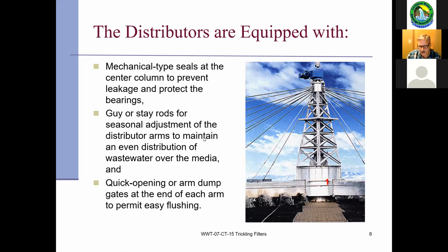Just trying to find a good picture for you. So this is the distribution system I was just talking about. So as this arm moves around, it's distributing the flow around throughout the tank. It's picking up O2 as it's dropping from this distribution arm onto the media. This media, like we talked about, could be a plastic type media, could be a rock formation, anything that will support that media growth. It's interesting. This would be your little walkway out to take a look on it, and it's just supported right on top of that media.